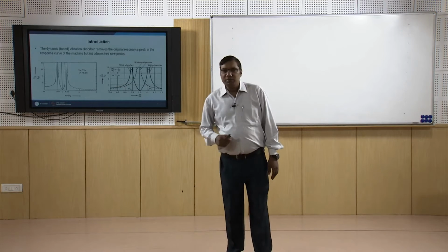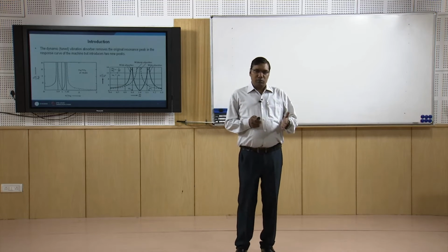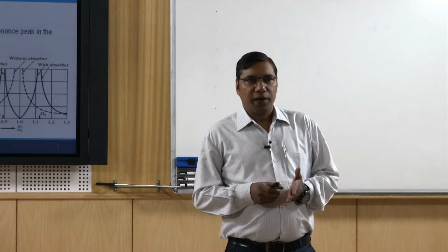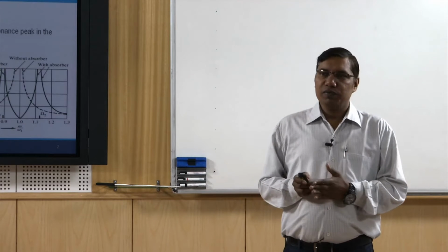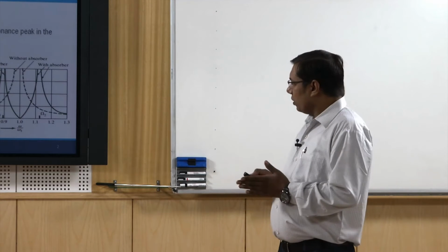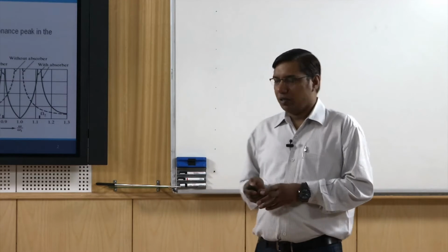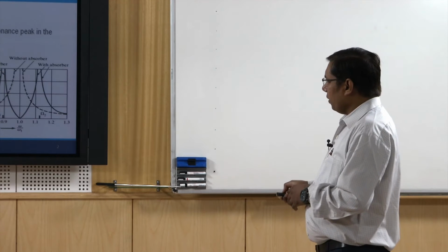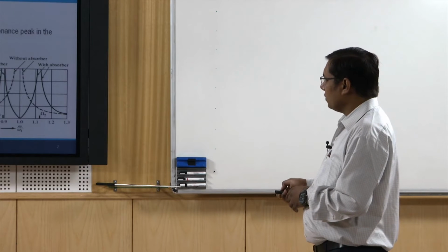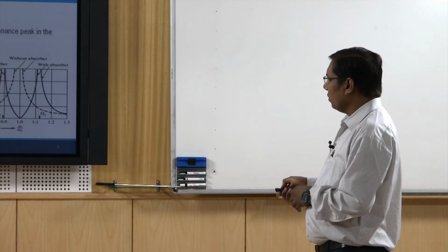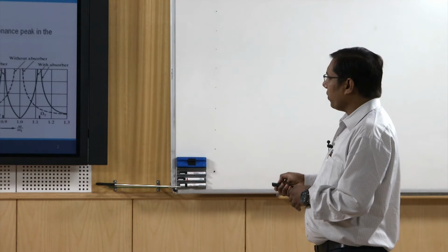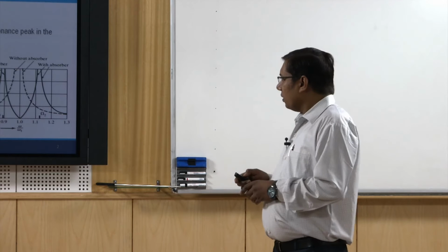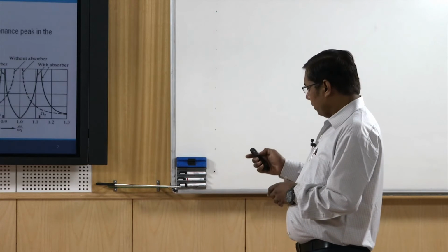when we start any machine, it starts from some low speed and it reaches its operating speed. Therefore, it passes through the lower resonant frequency of the system, for example here 0.8. Although its operating frequency is here, it has to pass through this frequency. So, at this frequency the amplitudes of vibration are quite high, quite large, and we can also see this from here